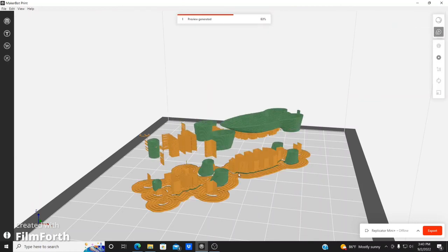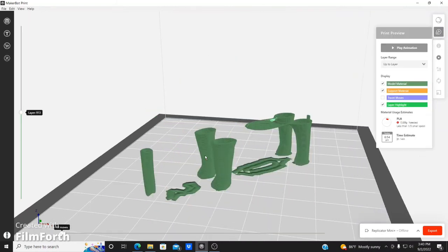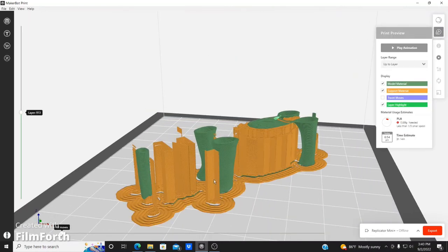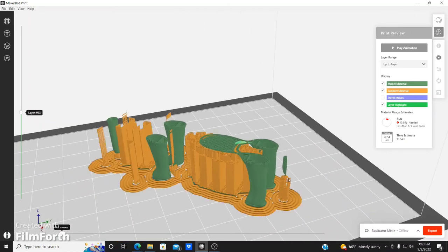Okay, there we go. So on the elephant, where it's creating the toolpath, that's my fault. But on the elephant, you notice that this will take a lot of material, and I would say this one will be a complete failure, because once you print onto these ones right here, it'll print out the foot. I predicted it, yes, but it'll fail on the trunk and the tail.